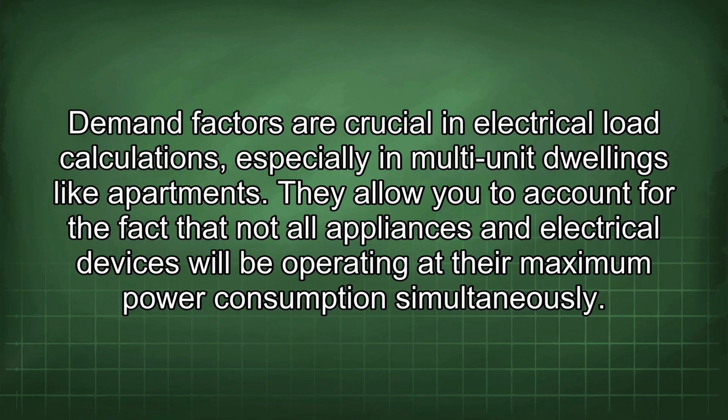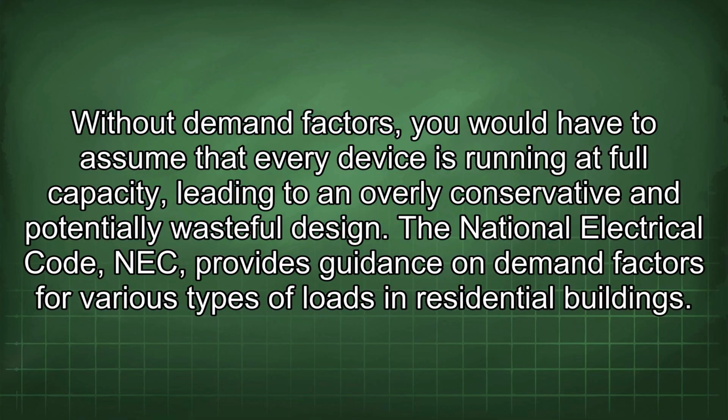Demand factors are crucial in electrical load calculations, especially in multi-unit dwellings like apartments. They allow you to account for the fact that not all appliances and electrical devices will be operating at their maximum power consumption simultaneously. Without demand factors, you would have to assume that every device is running at full capacity, leading to an overly conservative and potentially wasteful design.